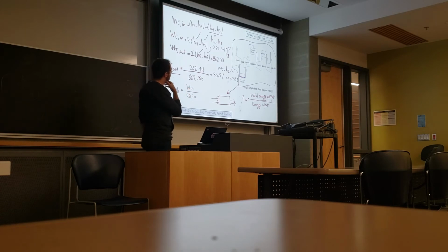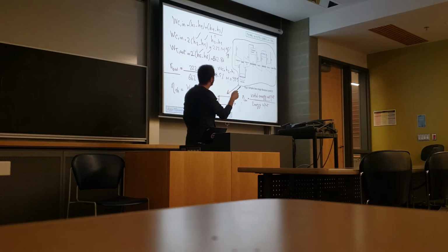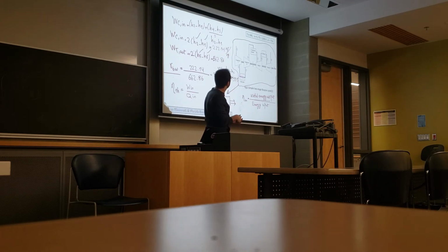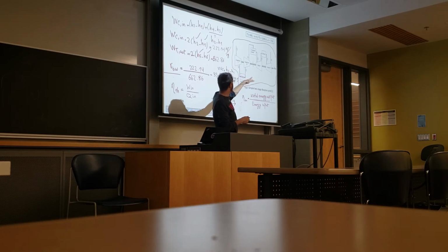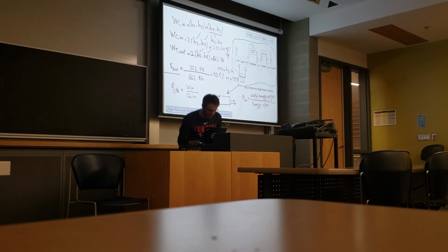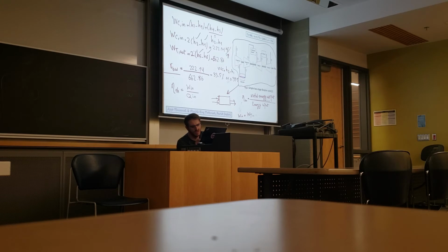So what is the net power generation? So we can write, yes, the output power generation is work of the turbines, so 2 turbines. But we can deduct the work of compressors, or we can write like the work of turbines are outputs and work of compressors are inputs, or we can combine them or deduct that as Wn. So Wn is work of turbines minus work of compressor. So this is the main output.